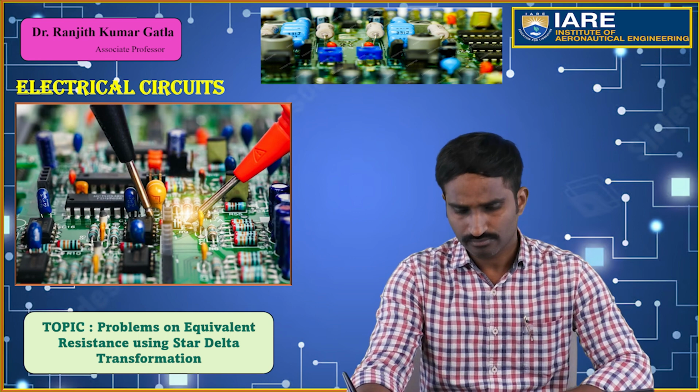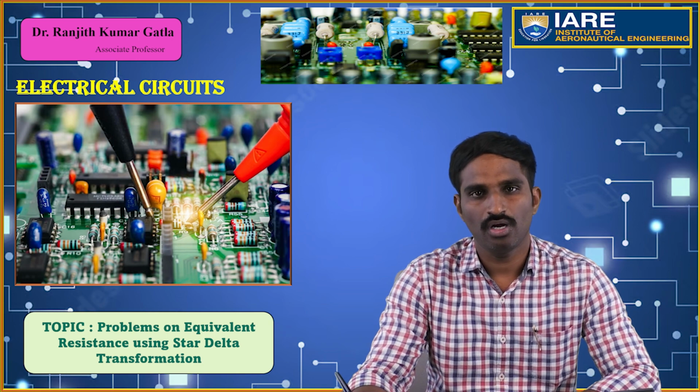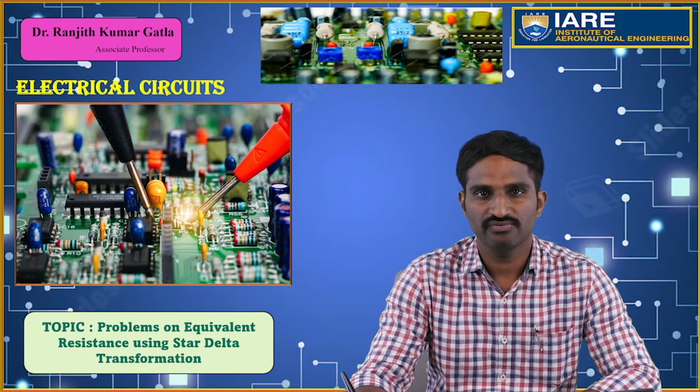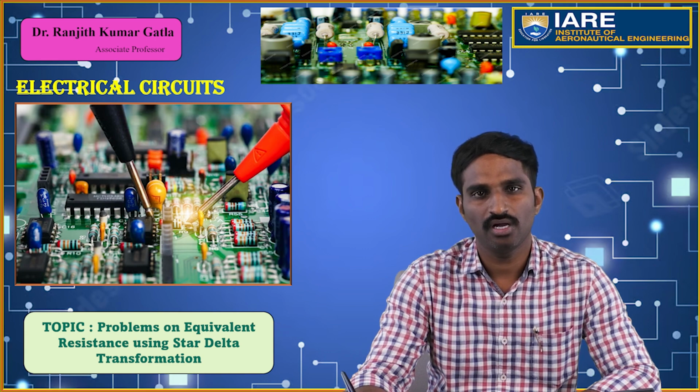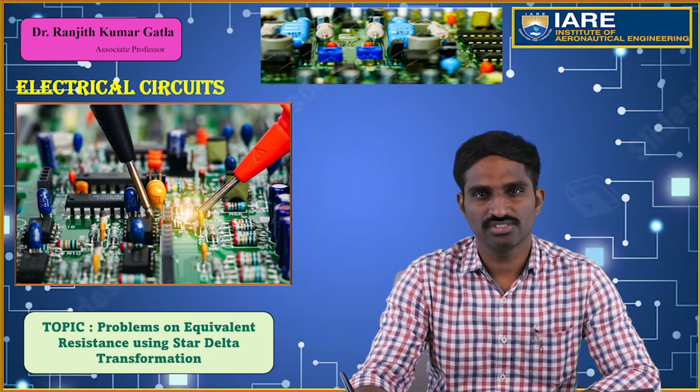Also, in the previous class we discussed how to identify the series connection of resistors and the parallel connection of resistors. For a series connection, if two resistors have one common node and the common node is not shared with any other element, then those two resistors are in series. Similarly, when two resistors have two common nodes, then they are in parallel combination.